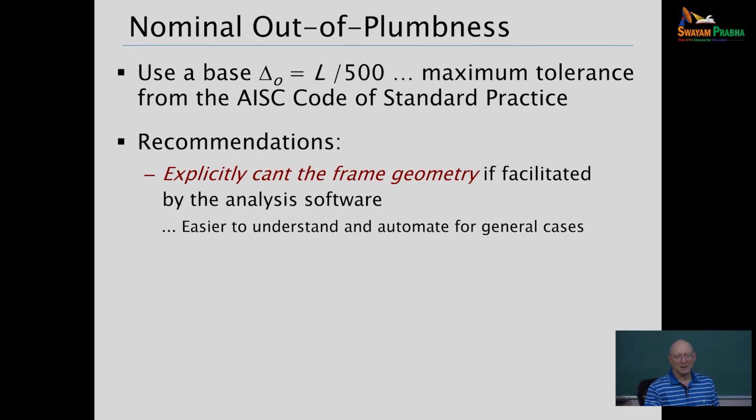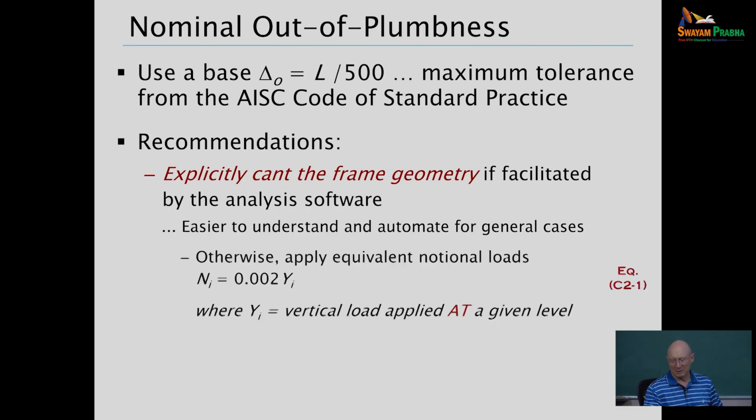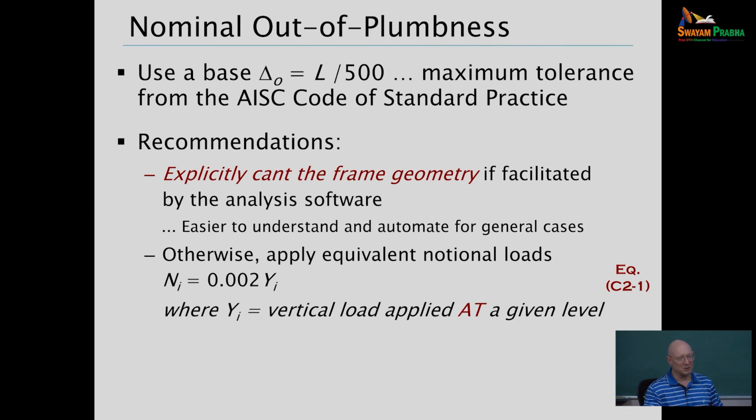Now, Consteel is very sophisticated in terms of implementing a whole lot of stuff from Eurocode, where it will basically put the imperfections in for you. And we'll explore just a few things with that, with stability bracing and a few other things, where we'll actually put an imperfection into the analysis model to run it. So I like to do that. I think it's clearer. That's what you're analyzing.